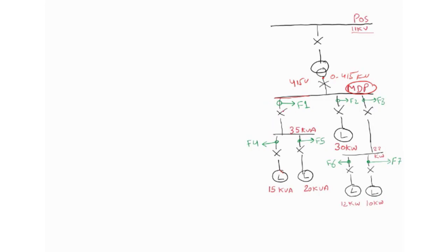So what is the meaning of load current or circuit current? This feeder is supplying power from this main distribution panel to this distribution panel, so it will get the supply from here and give the supply at this point. So there will be one circuit, or you can say one branch, or simply a feeder. In this feeder there will be two basic components: one is a cable and one is a circuit breaker.